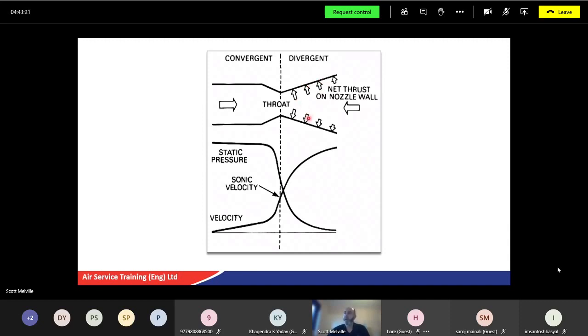So that's why no extra weight, because the aircraft can't afford too much weight. A normal aircraft will just have a convergent nozzle at the end of the exhaust, so it becomes sonic. Remember, that point becomes sonic. It becomes choked. Depending on the size of the nozzle, it provides the right amount of choke, which will cause a bit of back pressure, or total head pressure, and the engine is now breathing properly, providing enough velocity at the back end to push the aircraft forward.